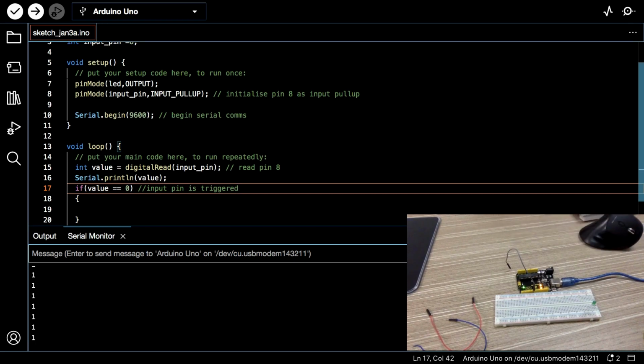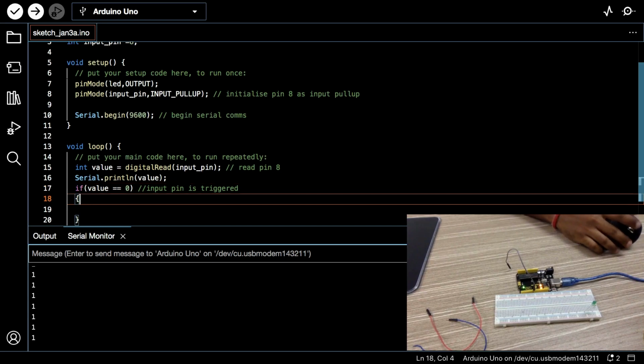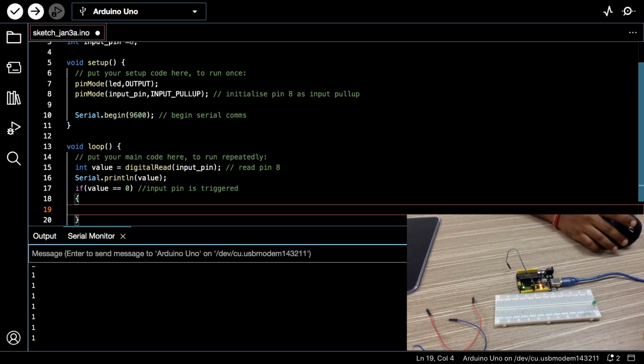And that's an input pin that we're just connecting to ground to keep things simple right now, so you don't have to invest in too much hardware. Granted, it's not too expensive, but still. If it's an input pin right now that you just connect with a jumper wire, tomorrow it can be a button, it can be a switch that you turn on here and turns on another light from another part of the world. Well, that's involving more IoT, which we'll get to, but we have to start small, unfortunately.